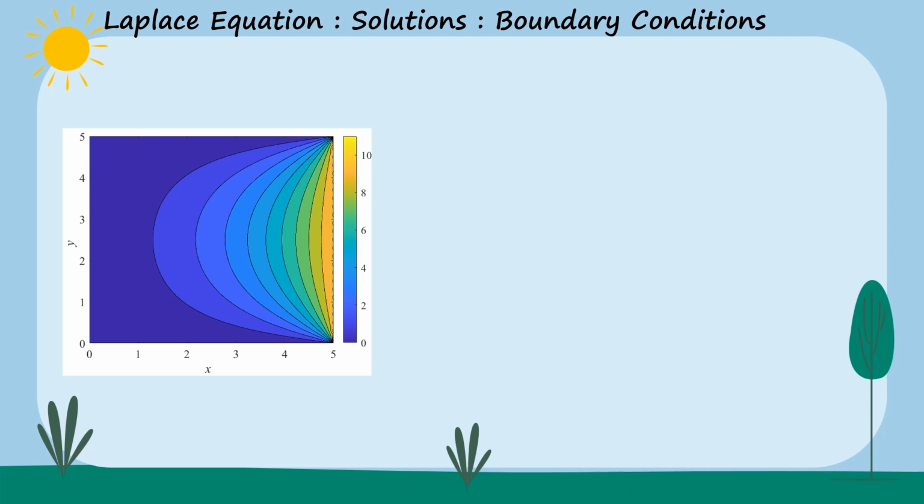Now, if we see the solution, all the boundary conditions are satisfied: 0, 0, 0. Now see the color in this boundary. That boundary color will be very similar to the color at 10. So what that means is that our temperature distribution, or not temperature, whatever the values, the distribution will be something like that. On all sides the boundary is 0, as provided, and the rightmost side is 10. So this is the solution.